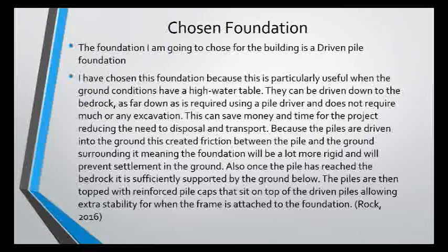The foundation I have chosen is a driven pile foundation. This is because it is a space and money saving process and works well when there are high levels of water in the ground. Also, this is a very suitable method for the steel frame structure that is going to be built.